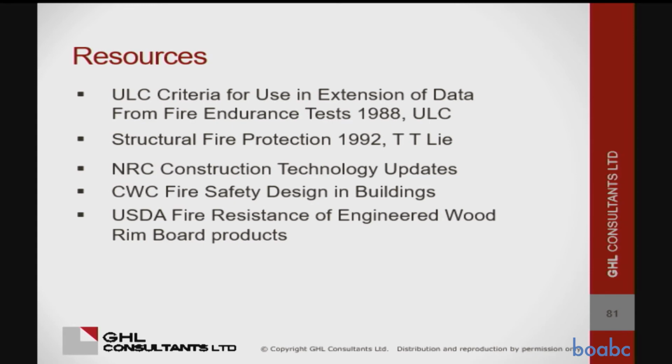It's this little book that tells you everything you can change about a fire separation that was tested by ULC and not screw up the rating or the listing. So it kind of follows Harmathy's rules, of course, right? You can add things, you can't take them away, those kinds of things. You can make the studs bigger, you can put the studs closer together, you can do this, you can do that.